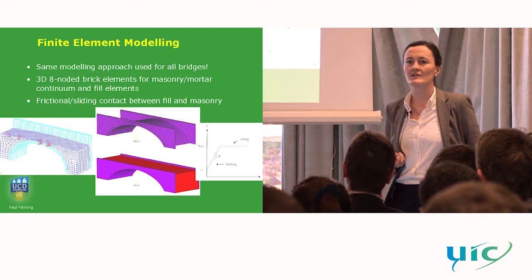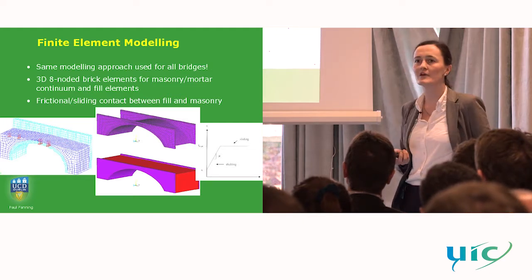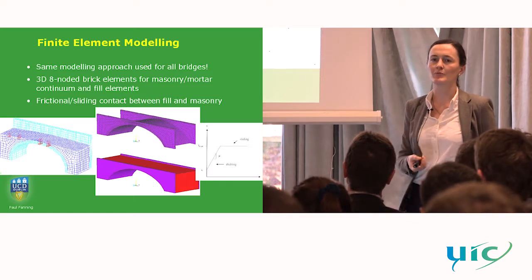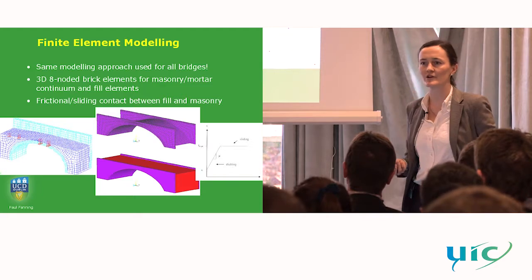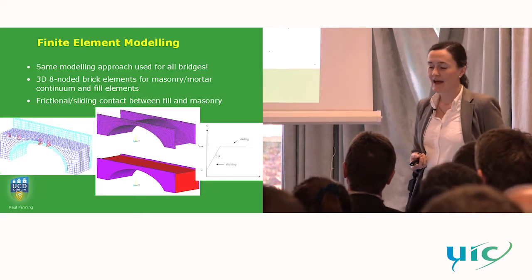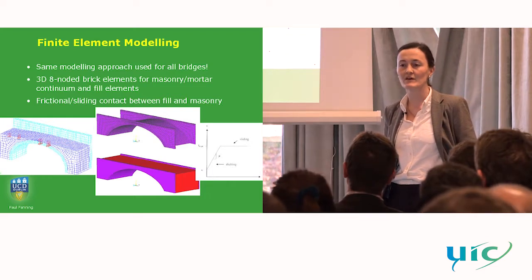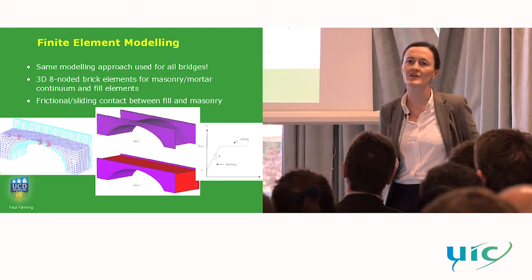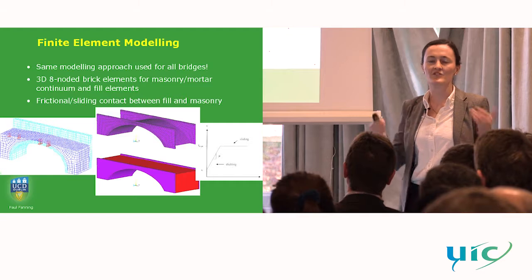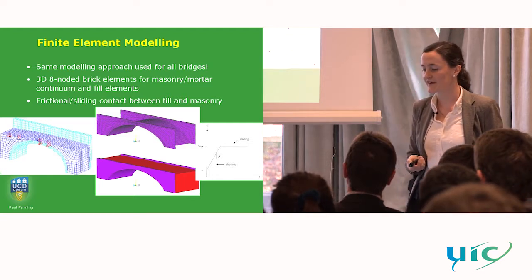That's a key distinction between some of the other approaches where often the fill is treated as dead load and earth pressures, and with this we're able to incorporate it as a solid element itself. And then we have a frictional sliding contact between the fill and the masonry material, and this allows the interface to stick and then slide once it reaches its limit.